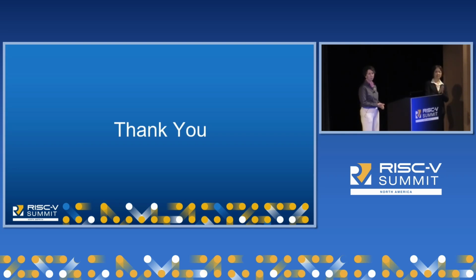So verifying CSRs is not included while verifying ISA, is that what I understand? The ISA compliance, how the instructions work, is a different assertion IP. Assertion of the registers themselves, their access, is a different kind of app, without considering the effect of instructions on CSRs. Okay, thank you so much. Yeah, there are two different apps to verify that.